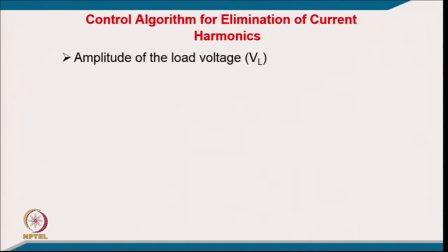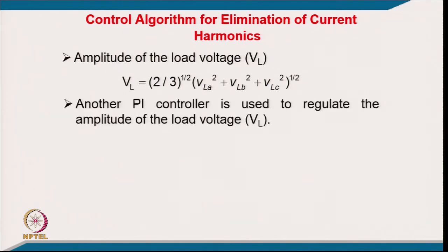And now coming to the amplitude of the load voltage, we are already measuring 2 line voltages, and from them we get the 3 phase load voltages, from which we calculate the amplitude of the load voltage by using this expression.